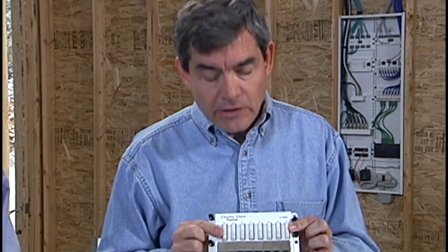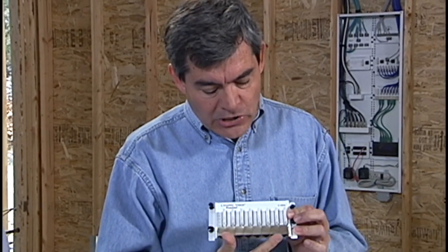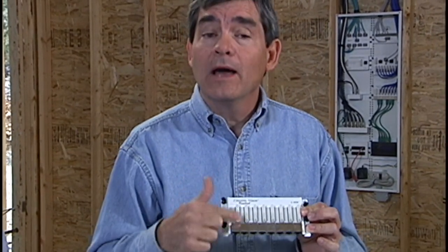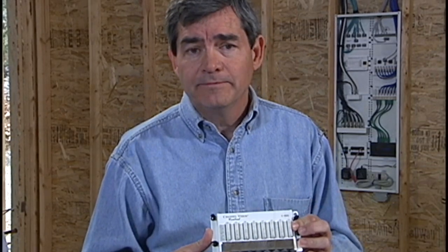Now, the second step is simply to add up all of the outlets and devices that need access. As we did our walkthrough, we determined the need for 20 data outlets. We'll also pre-wire network access at the thermostat, the security panel, and so on. Like the voice network, you'll need to determine how the data lines are terminated in the distribution center. We chose to use 3 of these data termination modules. They have jacks on them so you can select which data line is connected to which switch port.